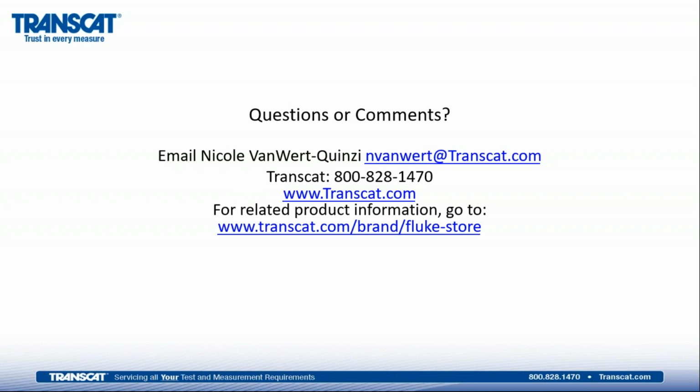Again, it's a little bit of a misnomer to say it's a signal, but it is actually the input that is interpreted by the transmitter that then converts that resistance or millivoltage that's measured into the 4 to 20 milliamp signal based on the programmed range of the transmitter that's in the loop. I hope that answers the question.